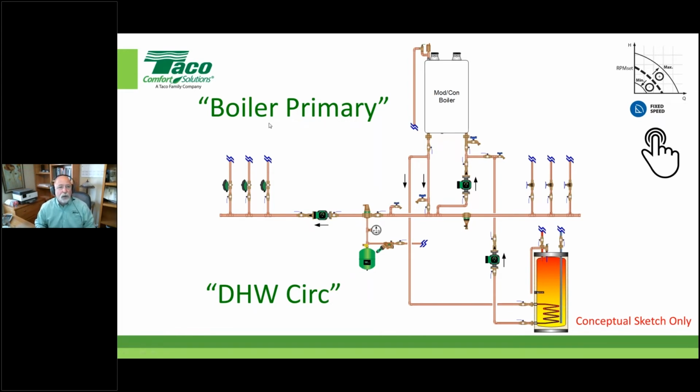All right. Okay, so again, I'll just go through. We got 3 pumps on the screen right now. So let's think about what mode, based on what you learned already, would be appropriate for these. And for the sake of time, I'm going to go through it pretty quick. We know this is not right, and I will cover that for sure. Okay, because look, it's got varying flow capability that pump's going to see on the secondary portion of the system.